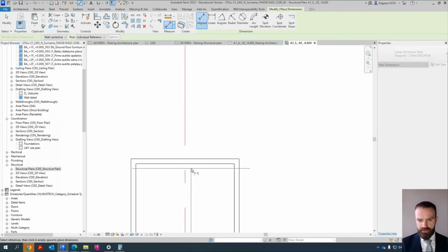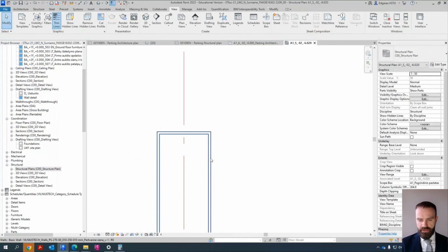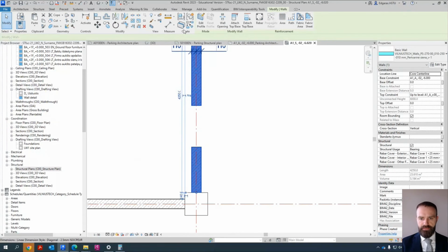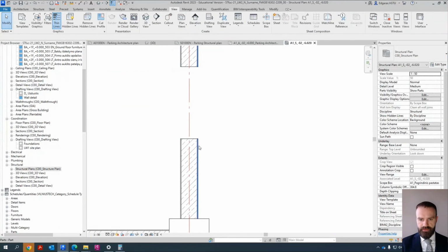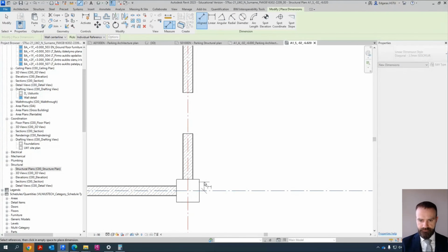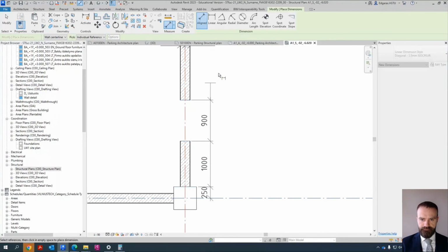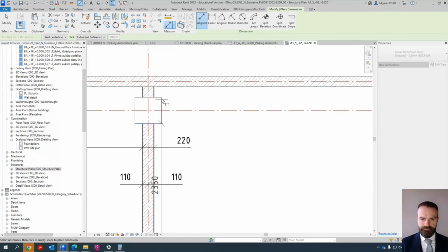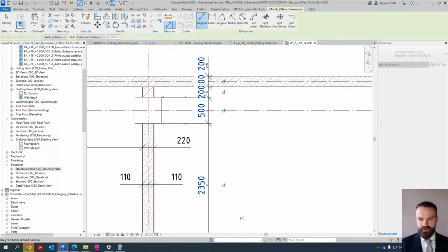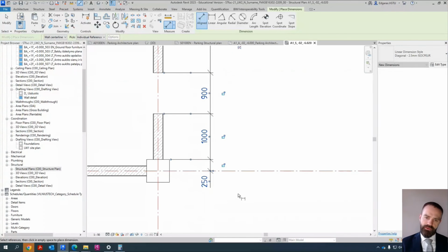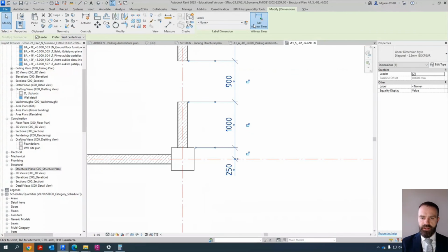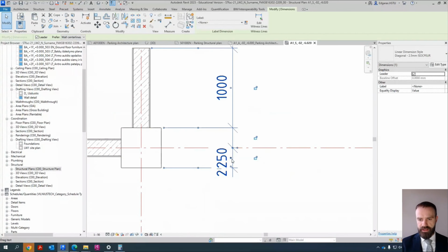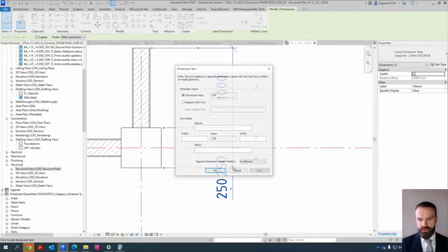So in this case, I also have some plastering on my wall. I don't need plastering part. So I just remove plastering, create the parts, and just show only the concrete part of my building. So in this case, the main task of structure drawing is to calculate the quantities, how much materials, structure materials I will need in my project.